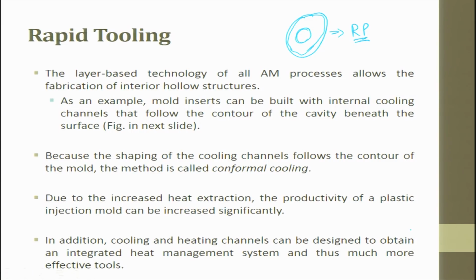By any other conventional technique, it is not possible without breaking open the shell. Only in rapid prototyping we do this layer by layer and make this part. Once all the layers are made, the interior material can be removed, either by making a small hole, or by pushing it into a liquid and washing it, which is also possible.